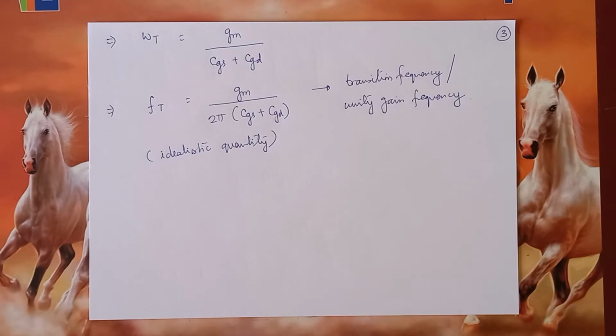So let us say if a transistor has an Ft of 25 gigahertz, you can expect it to work pretty well up to at least 5 or 6 gigahertz, if not more. So if your application is in the area of 5 to 6 gigahertz or less than that, you could definitely consider taking the transistor which is offering you an Ft of 25 gigahertz.